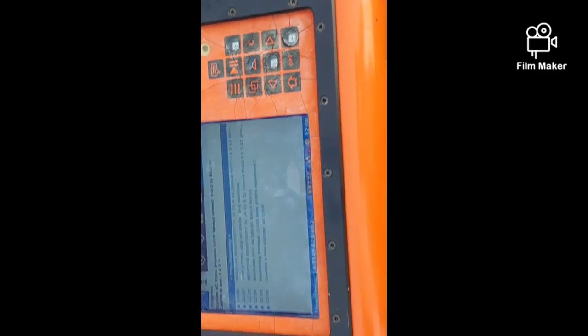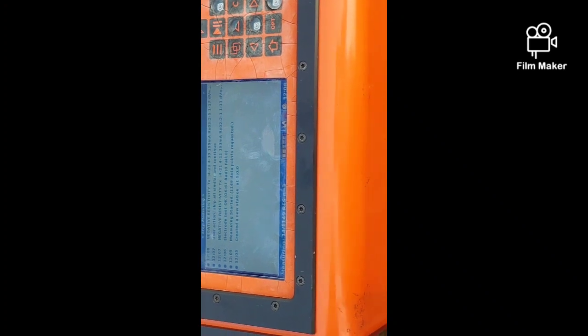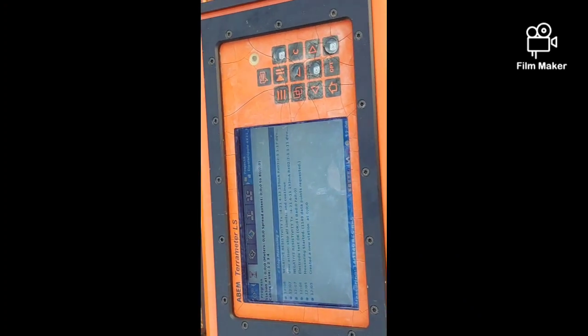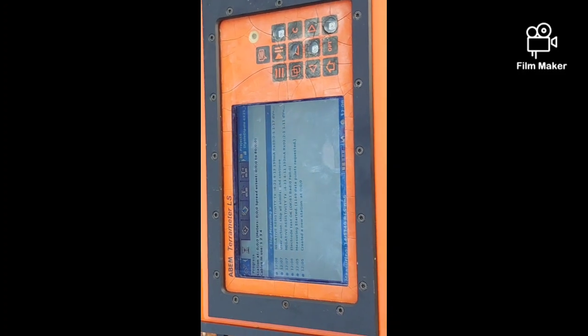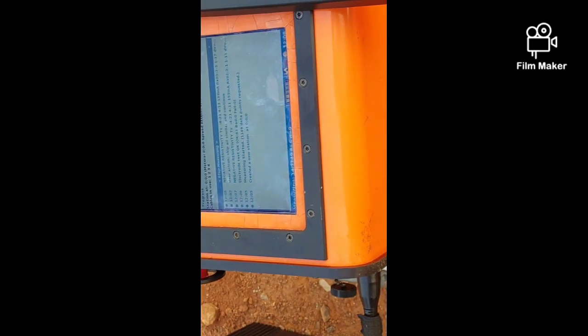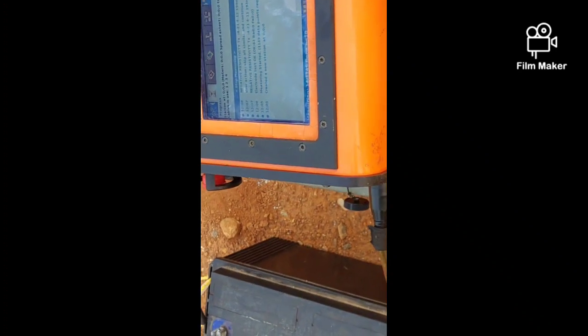Now we will measure all these negative and positive resistivity values. While processing, we will delete them. We'll remove the negative resistivity values, because negative resistivity is not possible. Here we only collect the data, not the showing data. Here only we will collect the apparent resistivity value.